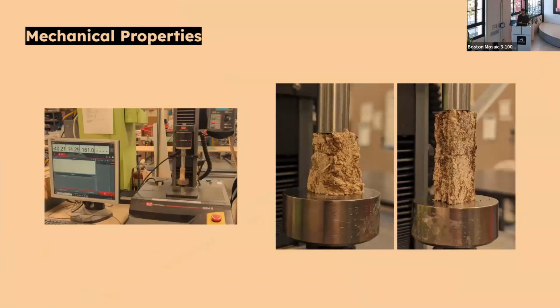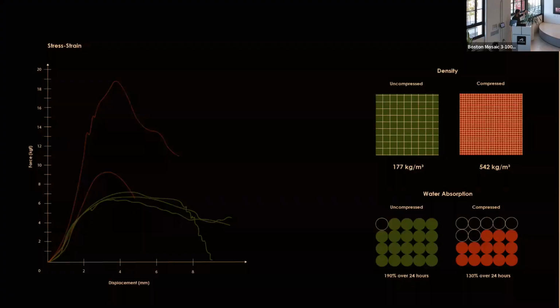So I have these two materials, the mycelium blocks and the mycelium sheets, and we want to compare these materials in terms of mechanical properties as well as experiential properties. This mechanical test was done at the Brown Design Workshop, where we had 5 samples. For the mycelium sheets, the sample had to be layered together to have the same sample size, which is about 20 by 20 by 40 millimeters. On the right image, you can see that there are 3 layers of sheets glued together, and it's loaded vertically. So I would expect the actual strengths to be higher than what you see here.